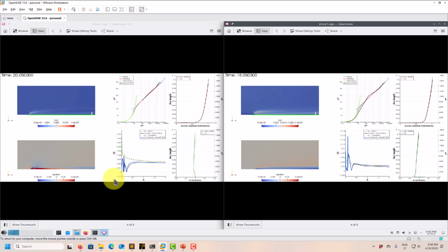But very interesting, the wall modeling case is not adding diffusion here. So this fluctuation is still alive there, but then you let it run and it will be diffused, dissipated by numerical effects, the mesh, the time step. But it's very interesting, because I would expect entirely the opposite case, that I would have those fluctuations here, and then here everything would be damped, disappear, be smeared. So this is a strange effect that we have.